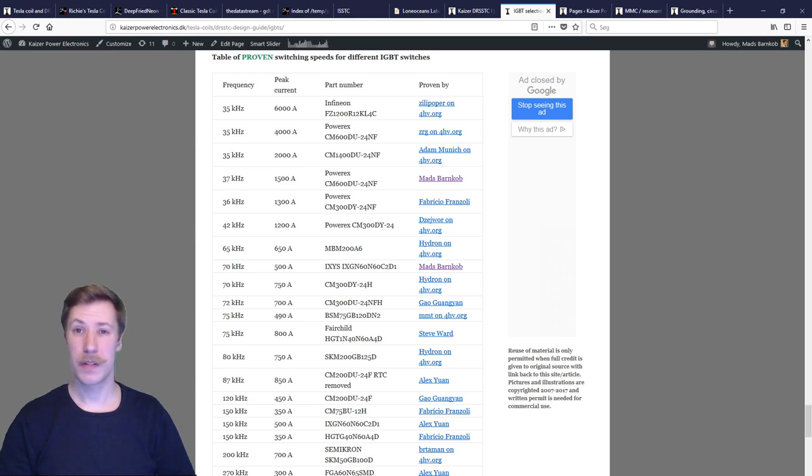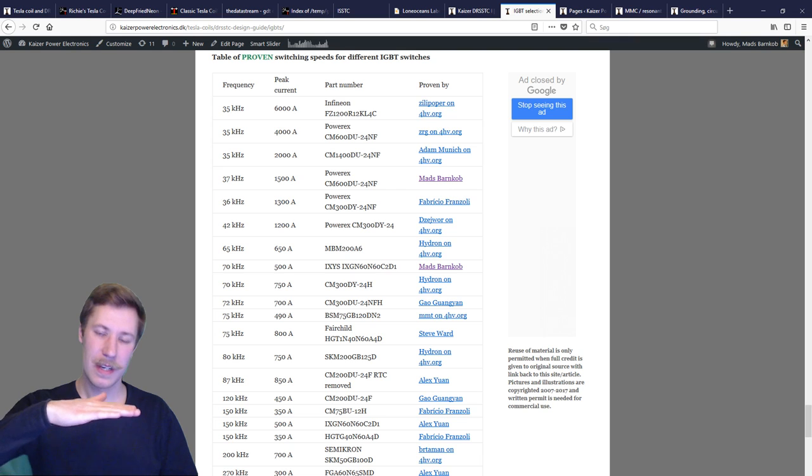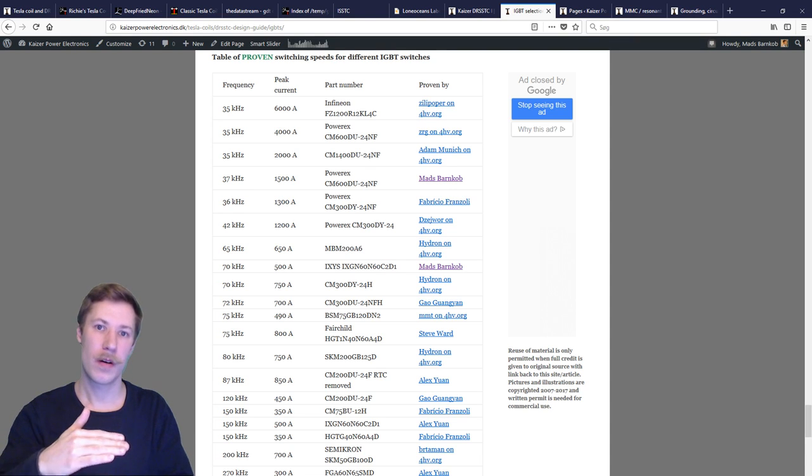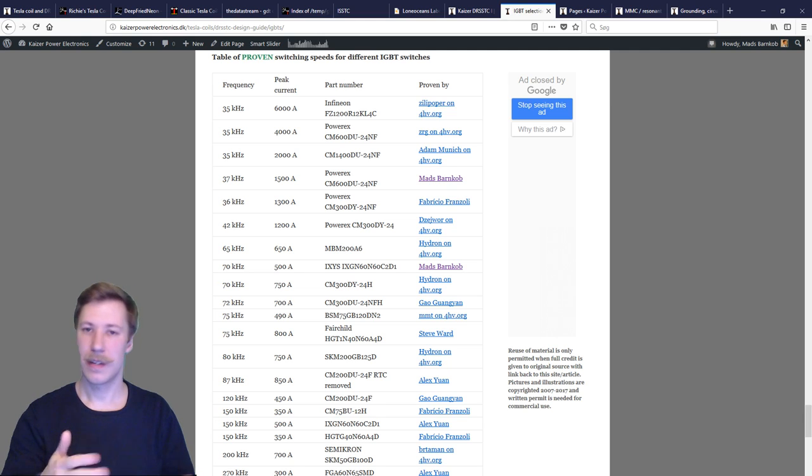And if you want to research this topic further, you should look into micro cracks in IGBT bricks due to temperature rise and fall. This is a really interesting topic where, through microscopy, it's investigated how the silicon die simply starts cracking underneath and loses connection with the copper heatsink, and then it will of course suddenly explode due to thermal runaway, as it simply can't get rid of its heat. That is a typical heat damage.